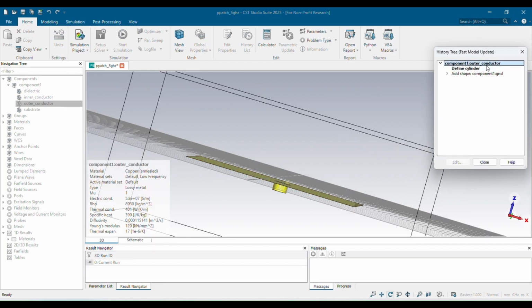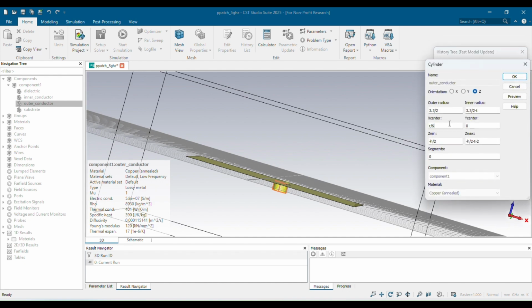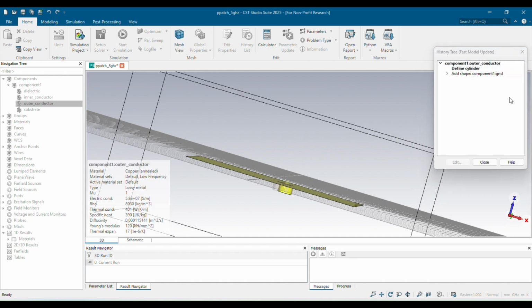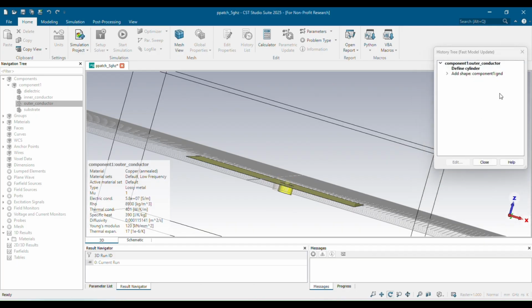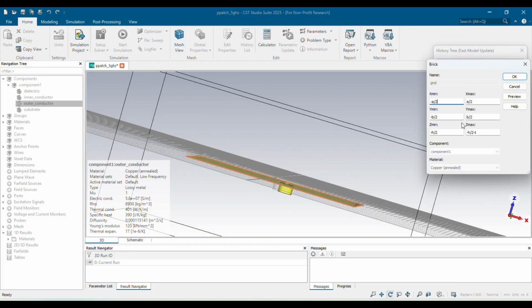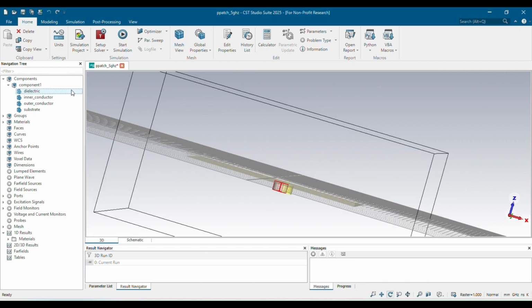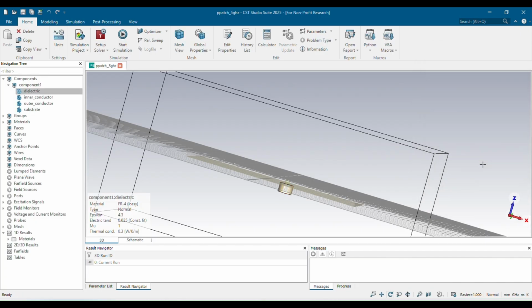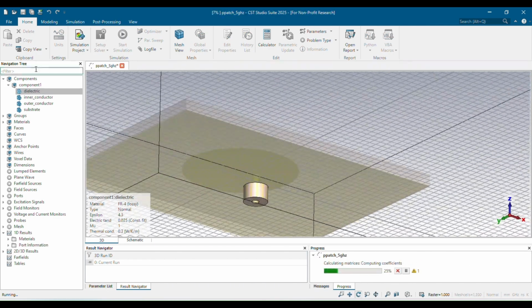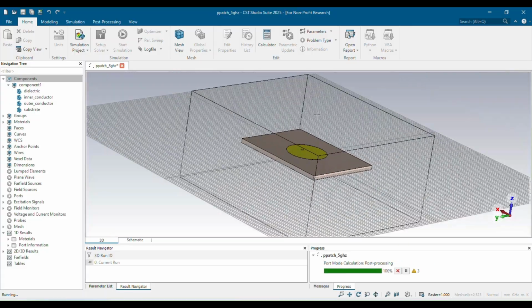Now a quick mistake in the video that I've done is I did not change the parameter of one of the feed line parts to r by 3, which is the cylinder of hole, I think. So that you have to avoid, and make sure that you change each and every parameter where r by 6 existed, and you can simply see from the simulation. Remember to press Ctrl S after each and every edit in order to maintain your work.